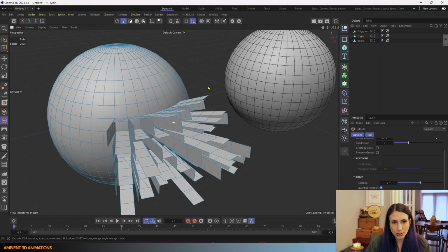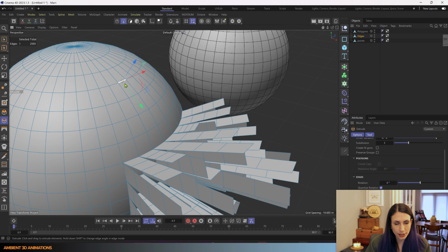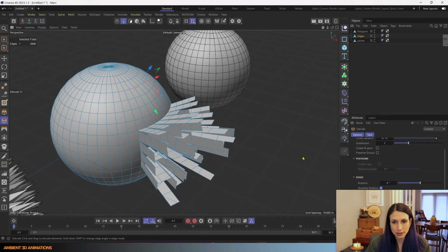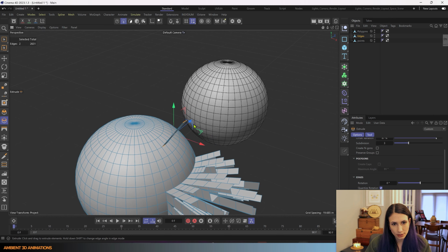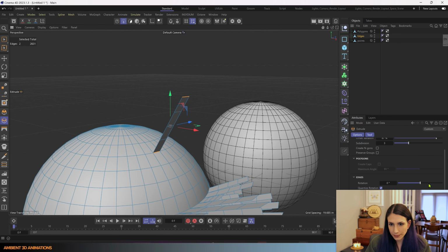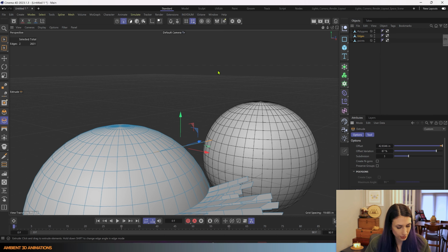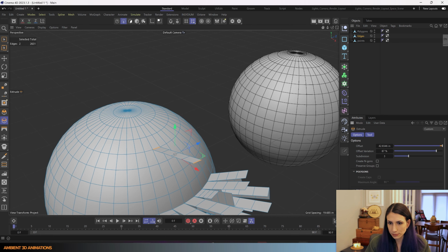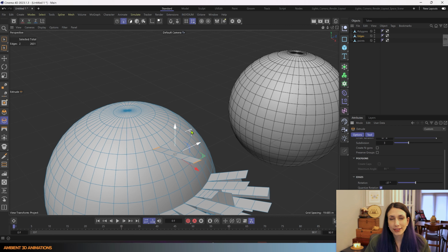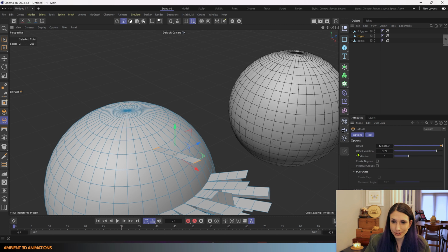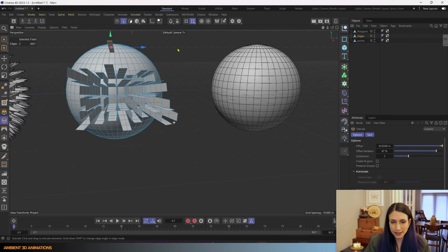This may be easier to show on one edge what this does. So for right now, I'm going to select a new edge, hit new transform. So I've extruded this edge, and now I can adjust its rotation, and that's adjusting the angle at which this is extruding. And we have a lot of control over it through those options there. Very powerful tool. The third way to control the extrude tool is polygon mode.